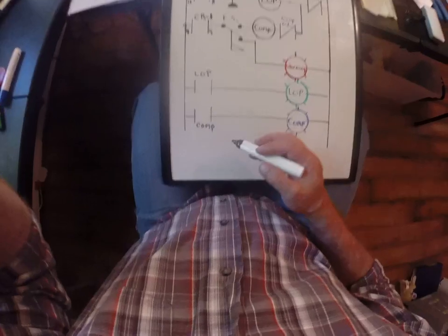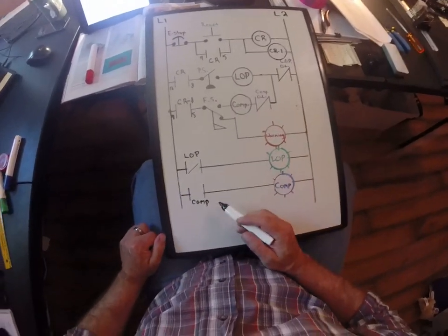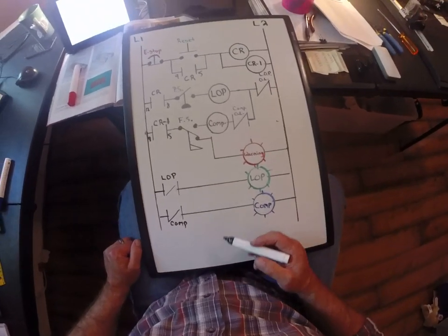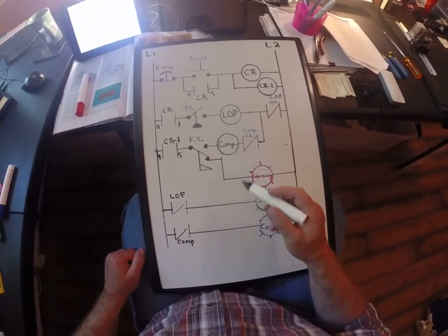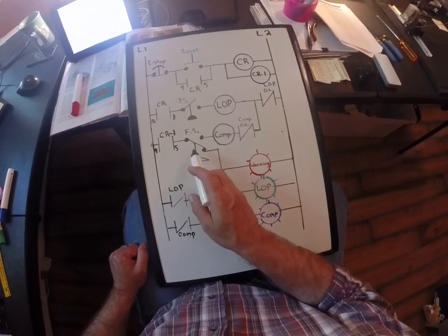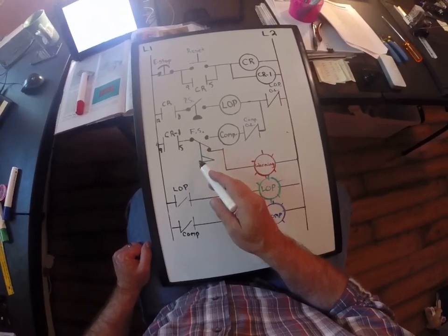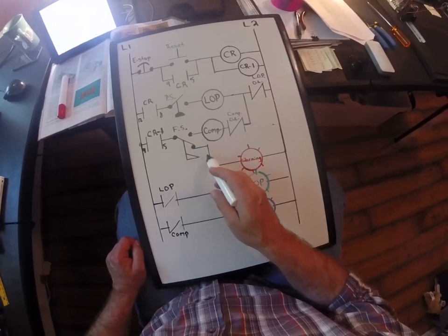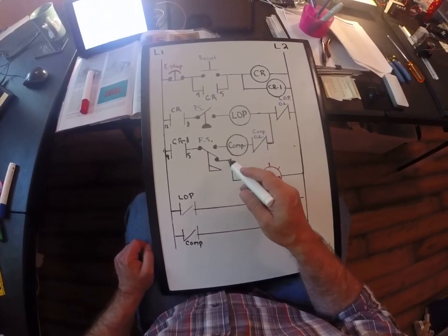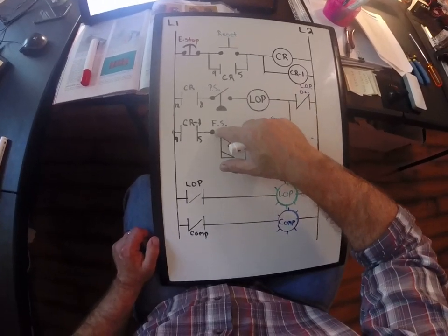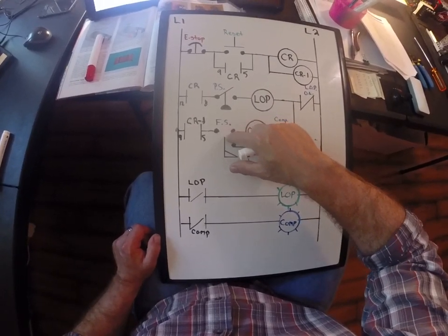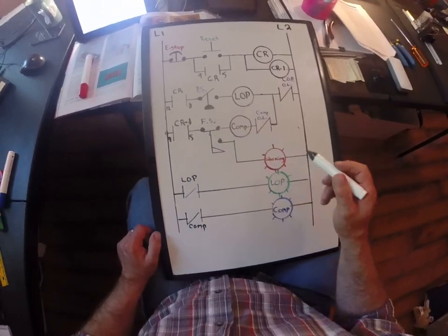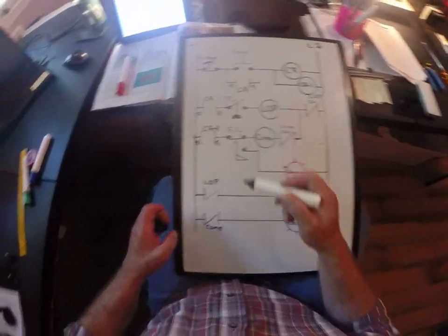We also know that when the compressor is energized, that will close, giving me my compressor light. And if I don't have oil flowing, this will drop back into its position where there's no pressure against that sail switch, or flow switch rather, and it'll give me a warning light. If oil is flowing, it's understood that that's a good thing, that this contact would close, giving me the compressor. We need oil for that to flow.